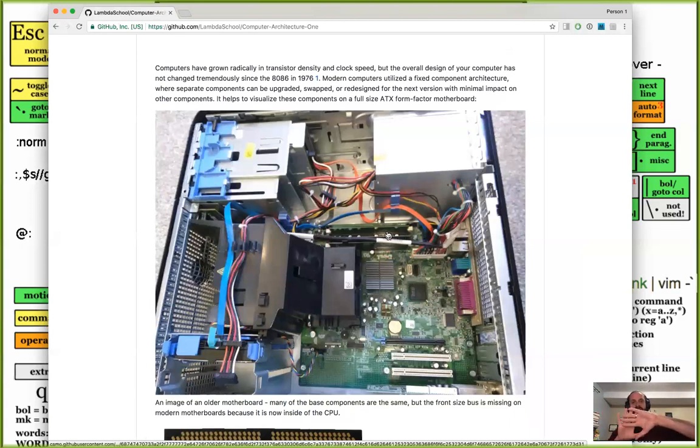I believe that actually at every intersection, there is a 64-bit word stored there. So what happens is, in memory, the CPU sends a message that says, reference the cell stored at this intersection of wires and this intersection of wires right here. Then in the next clock cycle, the memory controller points at that spot, loading the data stored at that location into its bus. On the next clock cycle, the CPU says, get that 64 bits and put it in me, essentially. So each clock cycle, the CPU can say, RAM, point at this position, and then RAM, read the data from that position. Or it can say, RAM, write the data to that position.